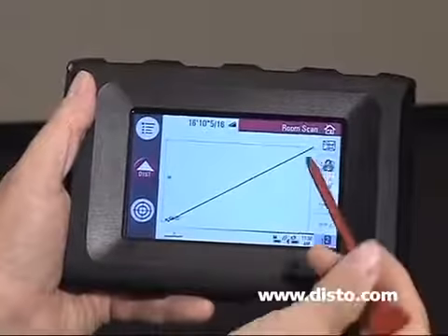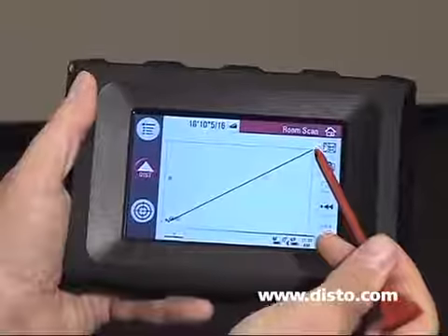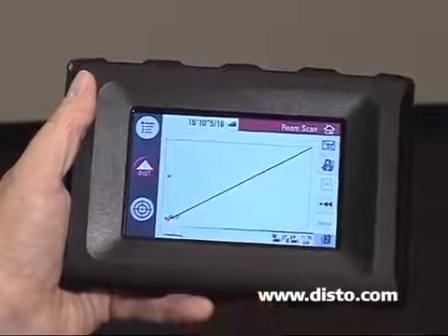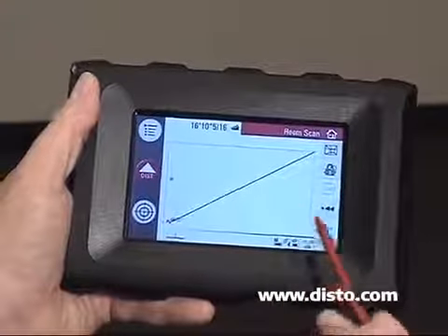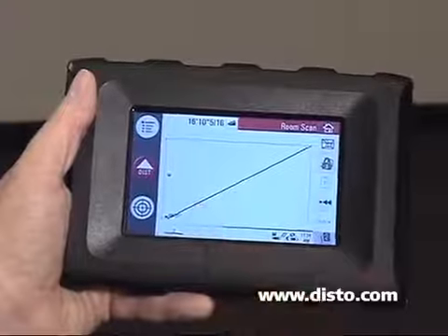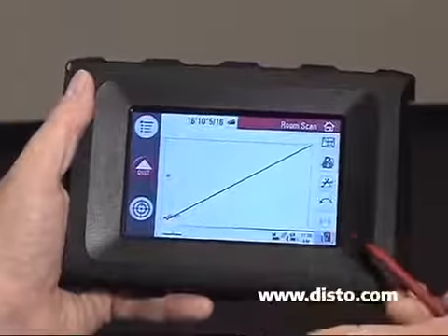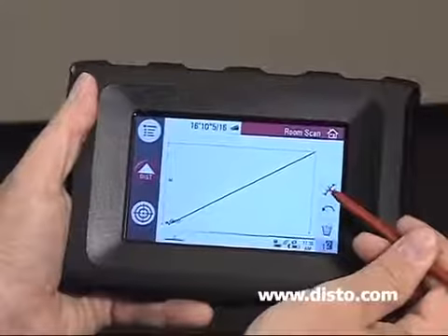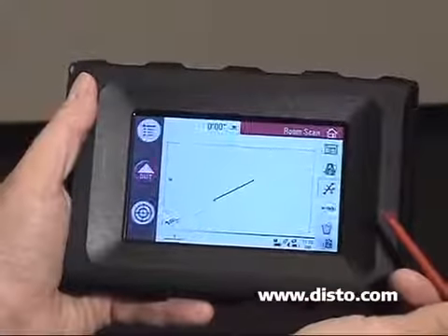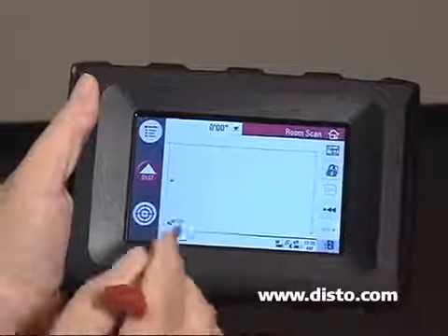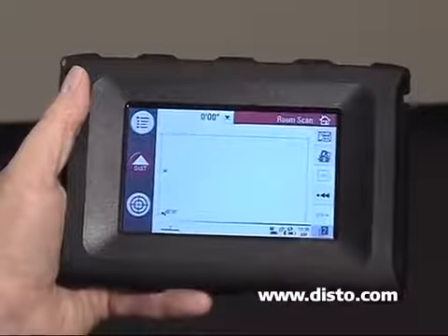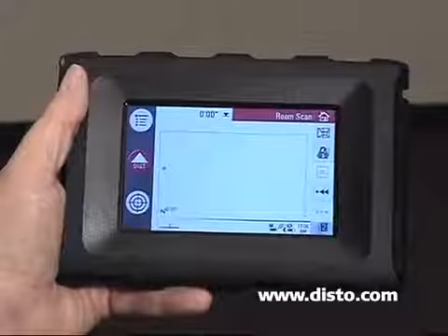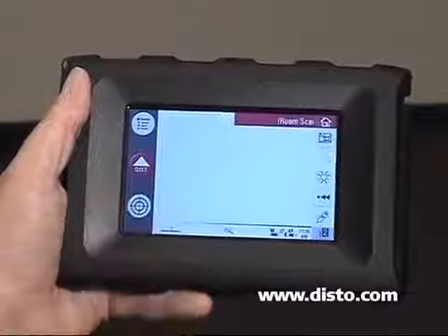Now you'll see I've got a diagonal line from that last point up there, which is point 3, to our new point down here, which is point 5. We don't want a new line segment from the last point to the new point. So we're going to drop over to screen 2, and there's a scissors with a cut symbol. We're going to hit that symbol. It's going to take that line segment out. So now down in the bottom left corner, I've got point 5 all by itself. Now let's go ahead and do the balance of the door.